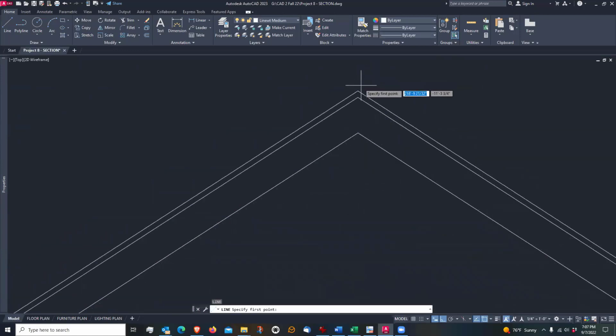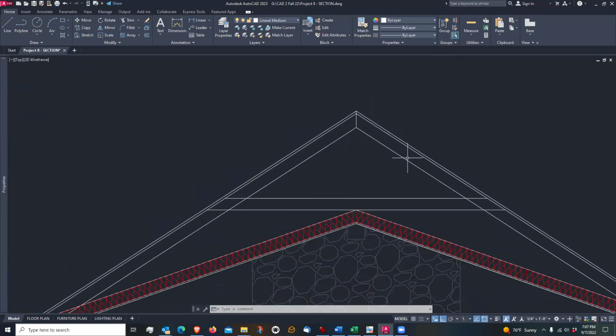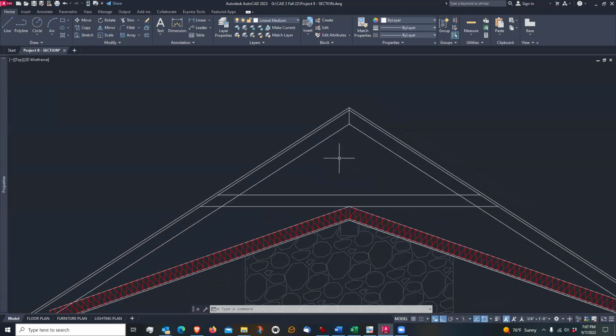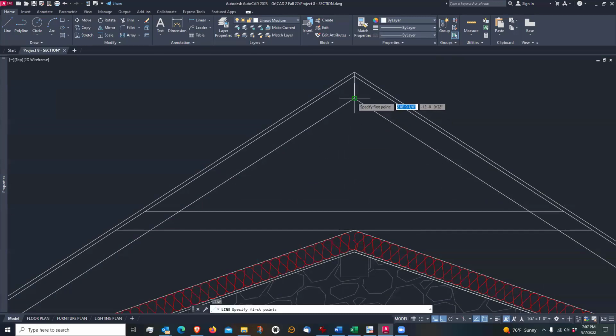And you know what? First thing I want to do is draw a line here. This is where this rafter and this joist butt up and connect to each other. There'll be a little connector up here that attaches them together. But running down below them is this vertical part of the truss. So I'm just going to draw a guideline here, and that's going to mark the center of that truss. And that truss is a 2x6, so it's 5.5 inches wide. So this is the center of it. So I need to go half of 5.5 inches.